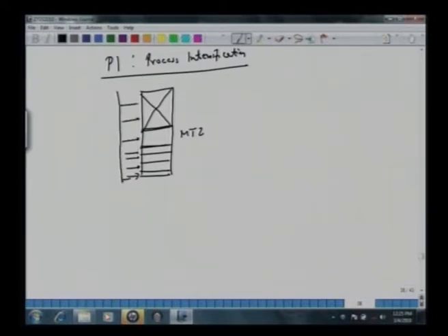All right, so this is one example of process intensification where you put some valves in each of these streams, and as the wave propagates, the feed can also be moved upward, up to this front, so that at any time whatever feed is brought, it's brought in contact with this mass transfer zone. In other words, if you have the feed here, then if this bed is saturated, the entire feed has to elute. There is an elution. So essentially this is ineffective. All right, this is a zone where nothing happens.